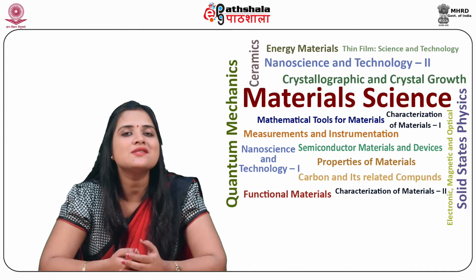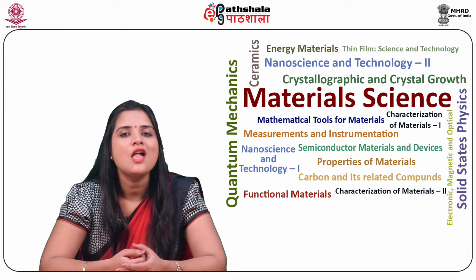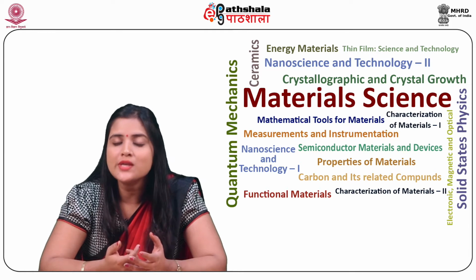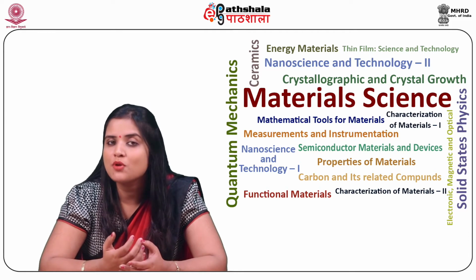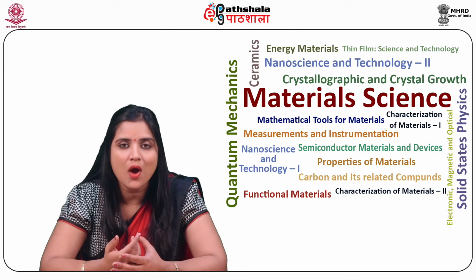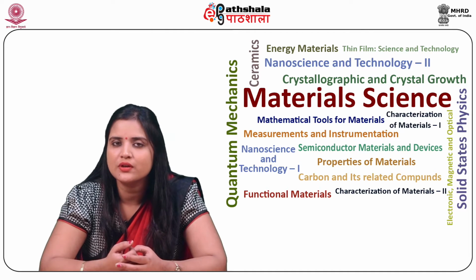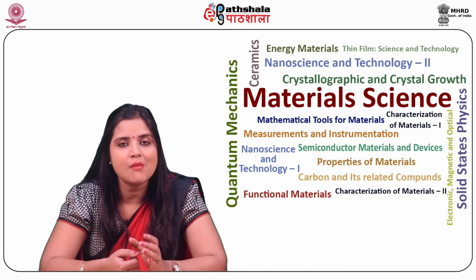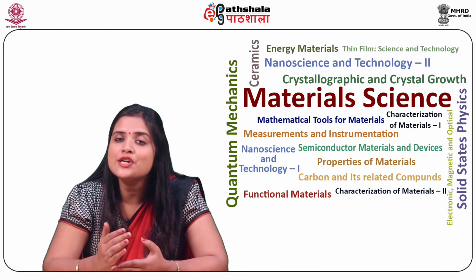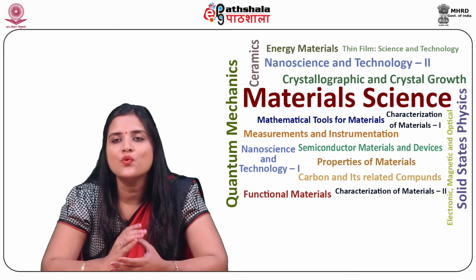Next, we will discuss the operational amplifier as voltage follower. It can be observed from equation 5 that the lowest closed loop gain that can be obtained from a non-inverting amplifier is 1 because the gain is 1 plus Rf by R1. So when the non-inverting amplifier is adjusted for unity gain, it leads to an interesting application of op-amp called voltage follower.